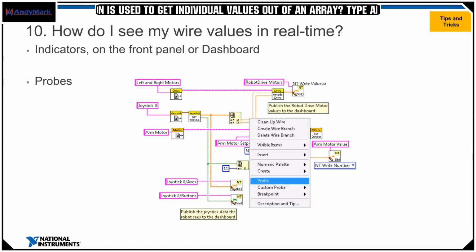And then my last point, still on number 9 with this dashboard: when you do want to add controls or indicators or graphs or anything to your dashboard, that's what this custom tab is for. It's intentionally left blank. It even says you can delete this comment. This is your space to add controls and indicators without messing up the way the dashboard looks. This will automatically integrate very nicely. It'll toggle back and forth from the full screen dashboard to these 2 individual windows, depending on what you have selected in the driver's station. So this is where I recommend putting any of those controls or indicators to keep your dashboard clean and functional and working correctly. You can put them anywhere else. Do so at your own risk.